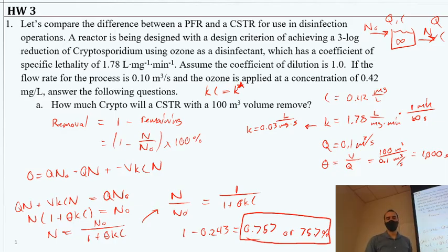That way our seconds line up when we have a theta here. It's 1,000 seconds times that value, 0.03 liters per milligram per second, multiplied by our 0.42 milligrams per liter for the concentration. Okay, does that make sense? Maybe. Yeah, it's okay. It's all good. I'm comparing it to the mass balance that we did at the very beginning, and so I'm just following. Yeah. Okay.